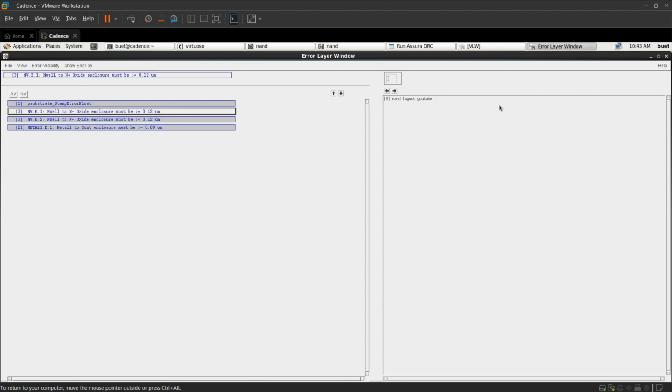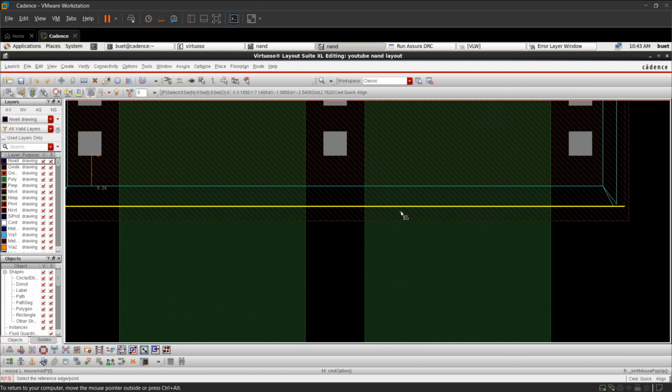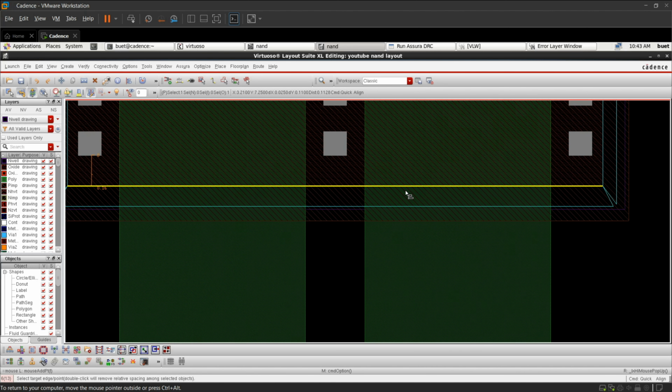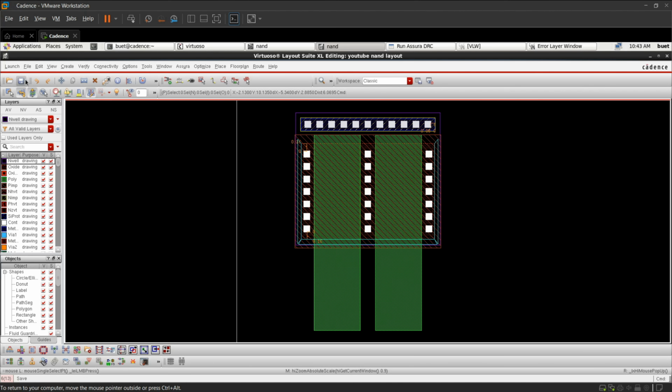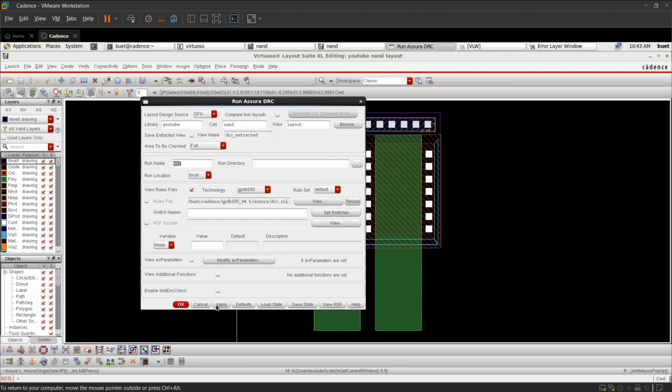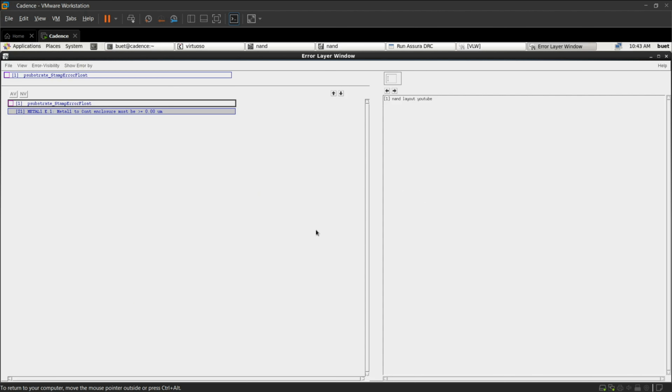Okay. Next error is not visible. Okay. It has to be 0.12 again. Select this edge. Yeah. Right now, hopefully for PMOS the DRC should be clear. Apply. Okay. Yeah, just forget about these errors. These two errors, we'll be looking into that further.